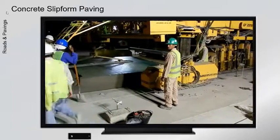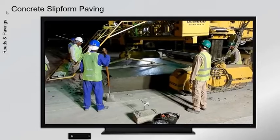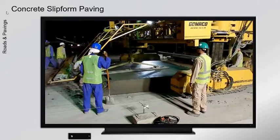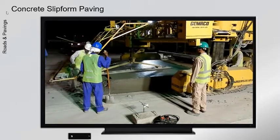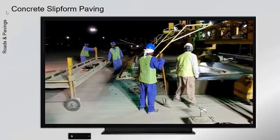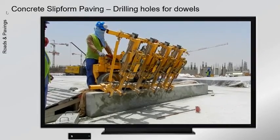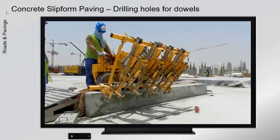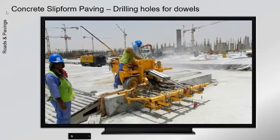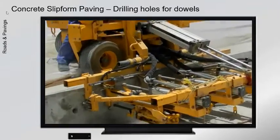Stop ends for transverse joints had to be made smaller than the slab profile to allow the paver to move over without dragging the stop end. Therefore, the stop ends were set 500 mm from the required locations and the concrete was cut at the required location. This is known as cut-back construction. Slabs containing inserts were identified beforehand and left out to be infilled later by handwork.